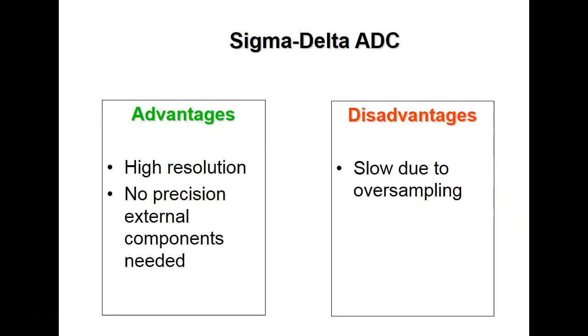So that's what this is right here. This is one of our analog inputs. I don't know if I got a program out there yet or not. Right now I'd have a problem because the power supply on this guy is a 24 volt supply, right? So I need to find about a 14K resistor to hook up in series so I'll get 10 volts. And we'll see that. Oh, I've got a box over there that's already set up.